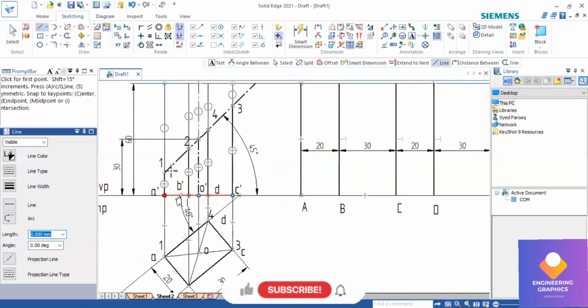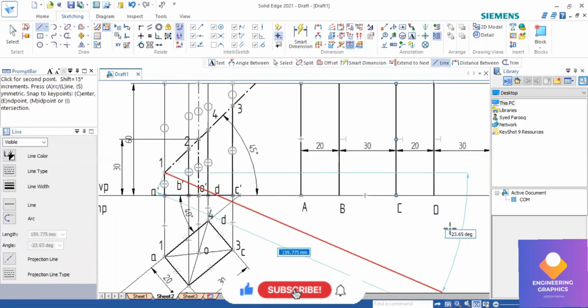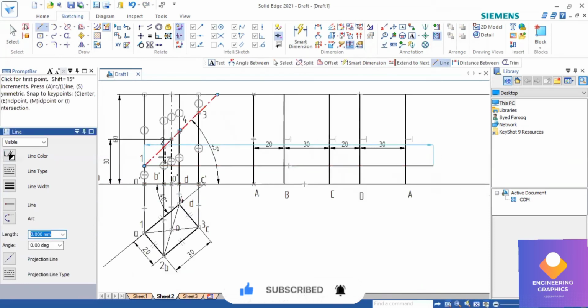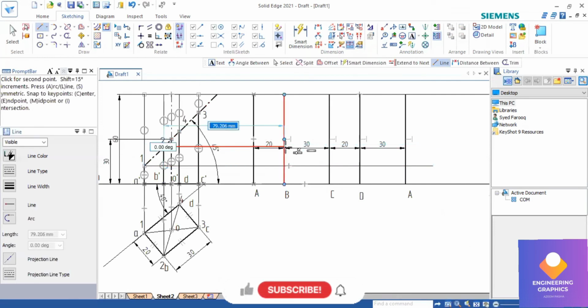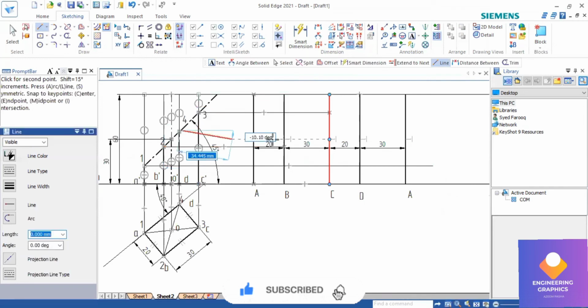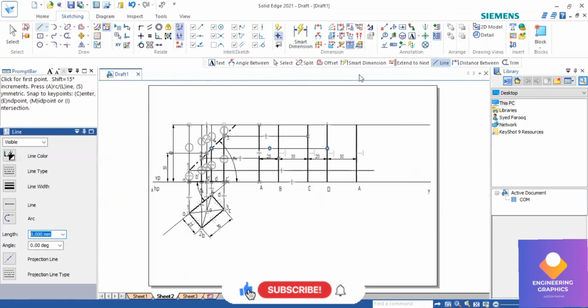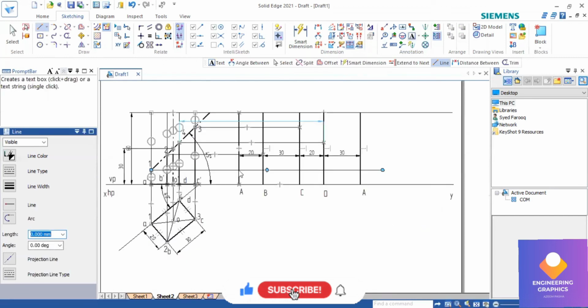Sometimes we can project it, sometimes you have to measure the distance. If it is occurring exactly on the vertical edges, we can directly project it, as we are getting in this problem. But if you do not get it on the vertical edges, then in those cases you need to measure the distance. But in this case you are getting everything on the vertical edges of A, B, C, D. So just by projecting the lines horizontally, we can get the exact points on the vertical edges. Okay, now we can mention 1, 2, 3, 4 here.